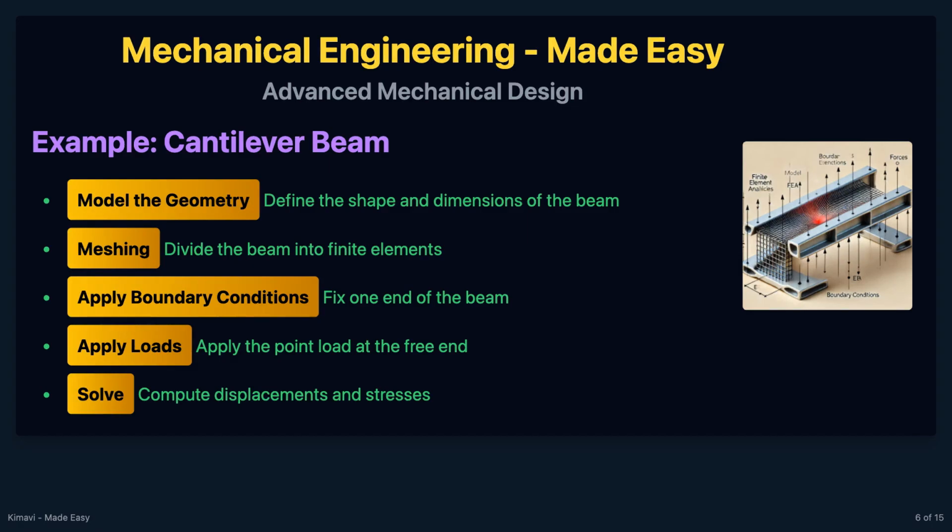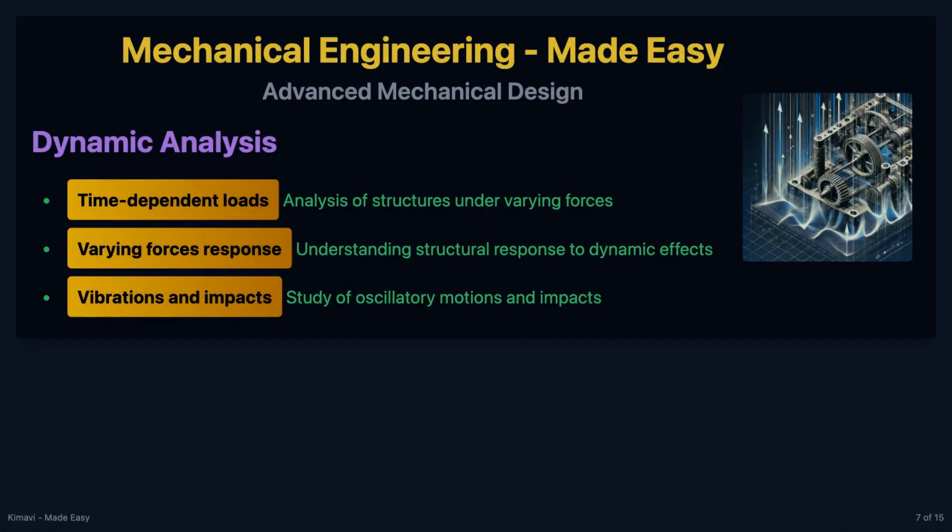The steps in finite element analysis would include modeling the geometry, meshing the beam into finite elements, applying boundary conditions by fixing one end of the beam, applying the point load at the free end, and solving to compute the displacements and stresses. Dynamic analysis deals with structures subjected to time-dependent loads.